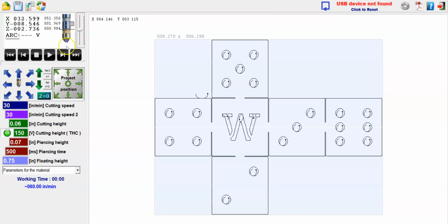Another feature that you're going to want to run with your system, especially as you get started, is test firing your plasma cutter. Now in this system, the space key is the torch on-off switch. So you'll notice up here, I'm going to go ahead and simulate the fire, and it'll give us a little tiny graphic here showing us that the torch has been triggered to fire by hitting the space key, and then I can click to hit that off again. Similar, I can just hit the key right here in order to get that to respond, but the space key is always nice to have around.